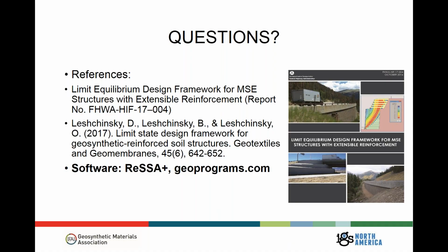It's also been compared to a series of centrifuge experiments and monitored loads. The thing to be very clear about is that this is a tool meant for strength limit state conditions. That means we're talking about imminent failure. We have to design to make sure the structure doesn't collapse or slide away. And when it comes to most of our structures, very few people are willing to volunteer their structure to fail. So in terms of monitored data for the strength limit state, there's not a whole lot.